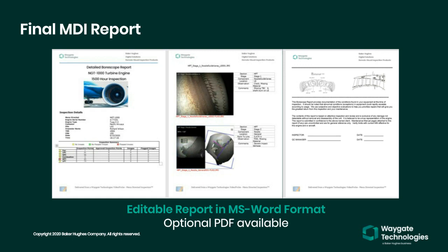Remember that an MDI does not need to be a full front-to-back inspection template. It actually could be designed to define a critical inspection point or two associated with some type of a service bulletin. The MDI potentially could contain reference images showing the orientation characteristics of the view of a component at an inspection point for which the author of the MDI would like to have captured.